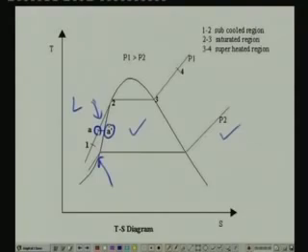That means if a liquid exists in subcooled condition, let's say its temperature is 30 degrees centigrade at some pressure, and we would like to find out the internal energy and enthalpy at these conditions. Instead of finding the subcooled properties, we can assume them to be equal to the saturated liquid properties at 30 degrees centigrade. This is a very useful idealization, and we will discuss it when we perform refrigeration calculations.